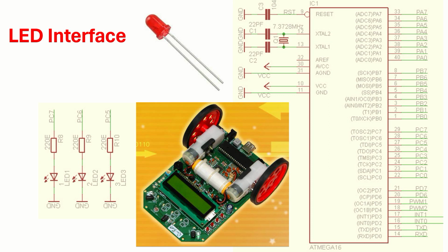For example, if you see the Deepavali time, the LEDs are connected to 230 volts. Even your spike guard, right? The spike guard also has LEDs connected to 230 volts. So don't think that there is a step down transformer converting it to 5 volts. Nothing like that. They have a potential of 230 volts AC. In between, they choose an appropriate resistor so that the current is limited.